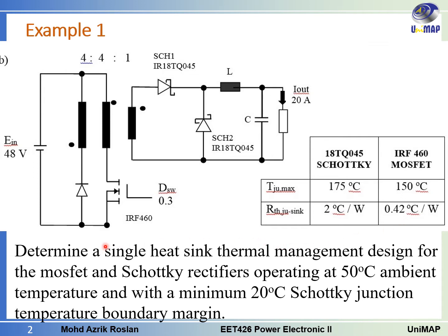In this question, it requires us to determine a single heatsink thermal management design for the Mosfet and Schottky rectifiers operating at 50 degrees C ambient temperature and with the minimum 20 degrees C Schottky junction temperature boundary margin.